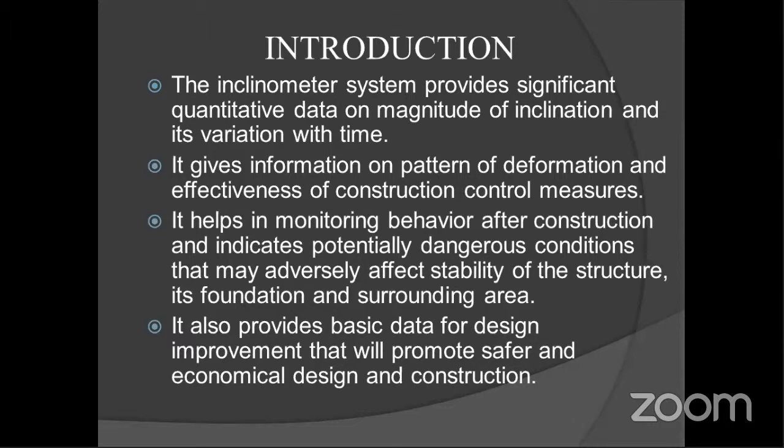It is very user friendly, so even a person having very little knowledge of geotechnical things can come to know how the wall is getting deflected and how much it is getting deflected. Mostly it should not go more than 40 mm, with the factor of safety I'm saying, because if it gets more, it will become difficult.